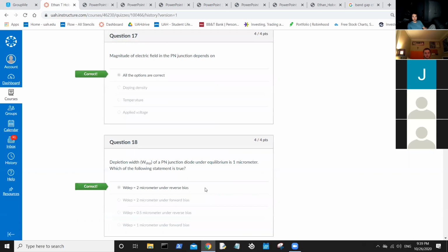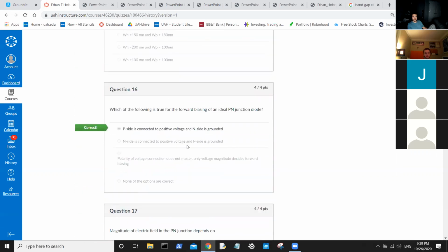These questions are super closely related because this question and that previous true and false question all operate on the same principle. When you're operating in forward bias, your charges are able to flow and the depletion region decreases, and the overall resistivity of your PN junction diode goes down in that direction. When you operate in reverse bias, the reverse is true. Your depletion region increases in size, your resistivity shoots up, and you almost have no flow. Very little current can get through, if any at all.